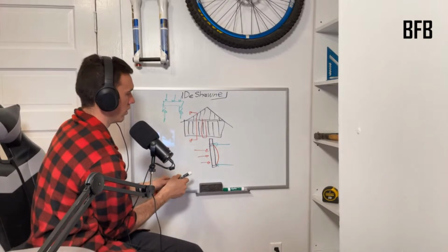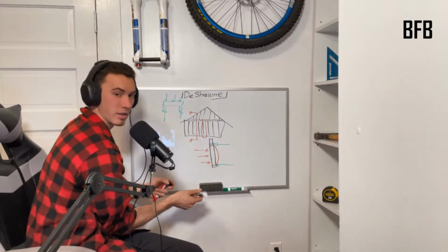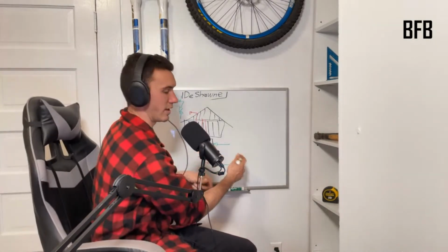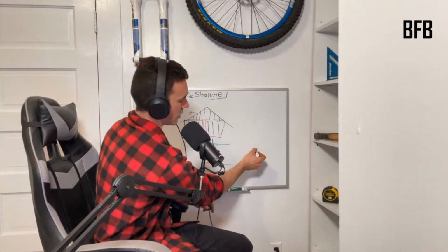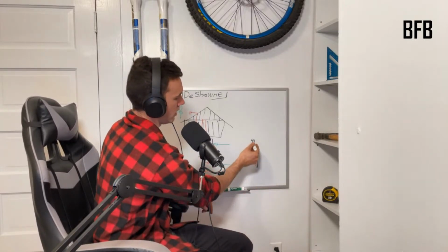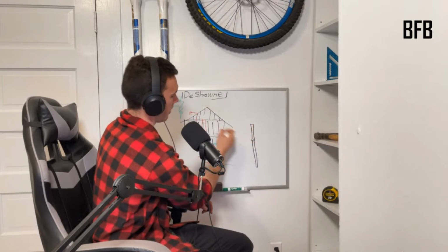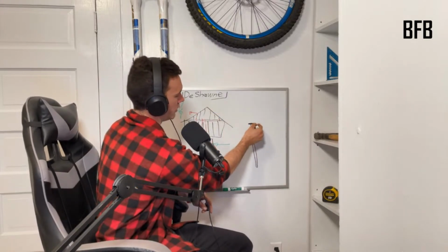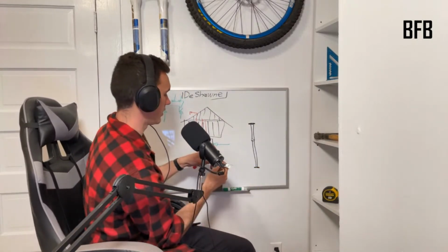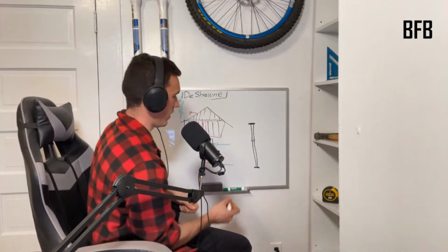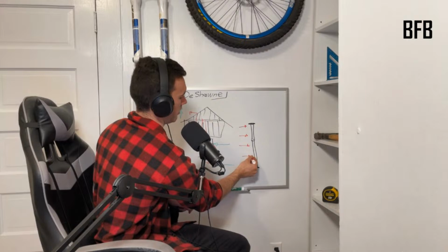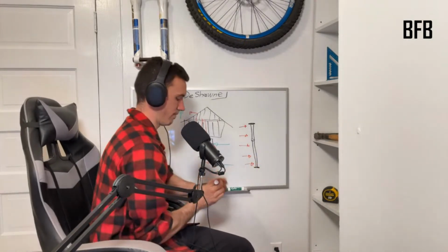So if I were to redraw this cross section, I guess over here, move my mic. So I'm going to redraw this cross section a little bit bigger. I've got my stud in the wall below, and then I've got my top plates, and then I've got a stud up top, and then I've got the roof doing stuff up here. Okay. So my foundation's down here. So what happens when I've got the wind force, that is the evil wind force, and it comes in here and it's trying to blow on this whole face because wind blows on surfaces and makes them get pushed.